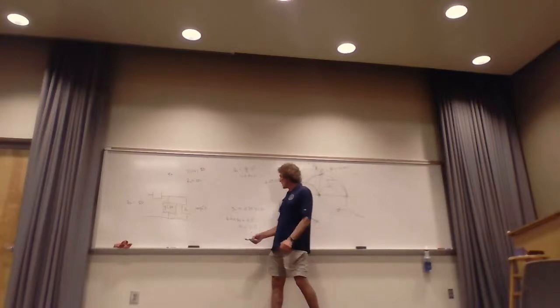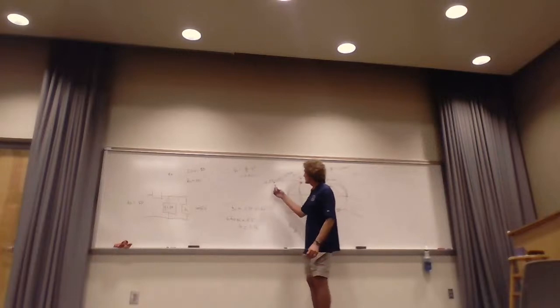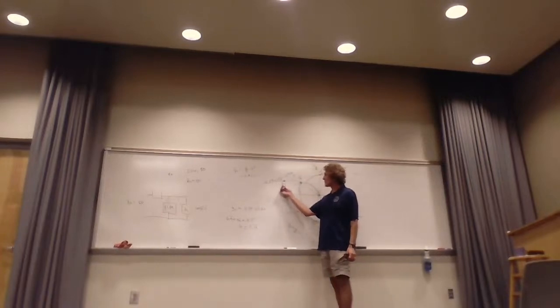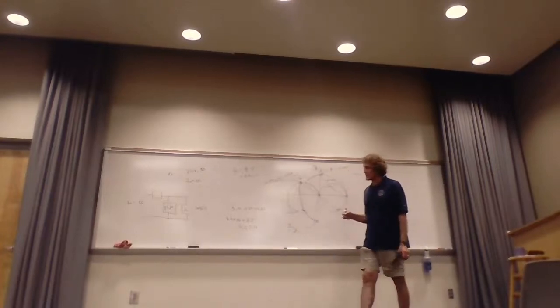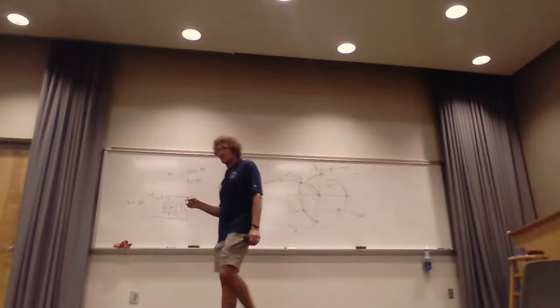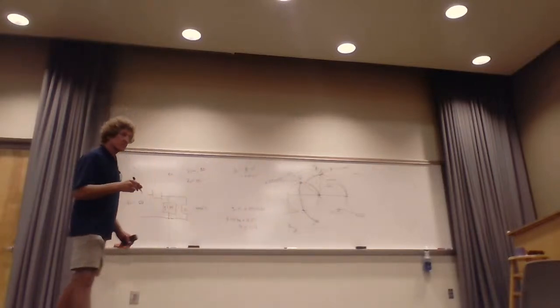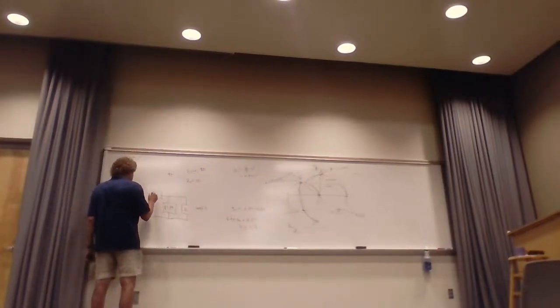Just take 1 over this, 0.34 plus j0.5, and tell me what you get. The real part should be 1. Let's do it. That's what it's saying. And what do you get for the imaginary? 1.36. Minus. Yes, sorry. Minus j1.36, right? That means we have to add an impedance of j1.36, correct?